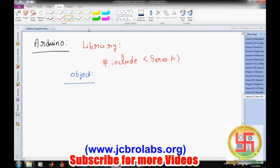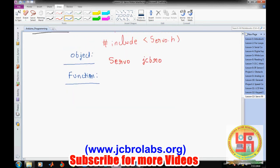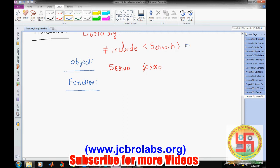So the object is created by taking Servo, and then let's say we have created an object called JCBR. This JCBR is a Servo kind of object, and this provides several built-in functions to interface this motor. One more thing is there: this library only supports pin number 9 and 10 of Arduino.